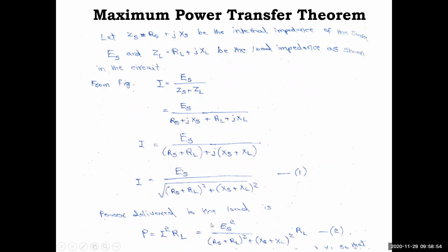That's why this left part is completely 0. And the second part, with minus: that is the same formula, u is ES square into RL. This part again does not act, so it will be 0, and in the other part you have 2 (XS plus XL). XL becomes 1, since dXL by dXL gives 1. So 2 (XS plus XL) with the minus sign will come in the numerator.